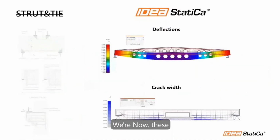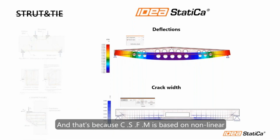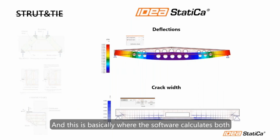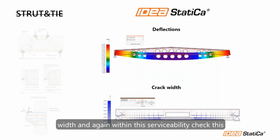Now, these capabilities that have been shown are not the only capabilities that are able to be done within Detail. And that's because CSFM is based on, again, nonlinear analysis. Two of the most important additional capabilities are for serviceability checks. On the top, we have deflections, and this is where the software calculates both short-term and long-term deflections directly within the model. At the bottom, we do have crack width, and within this serviceability check, this is often a headache to be able to do by hand.